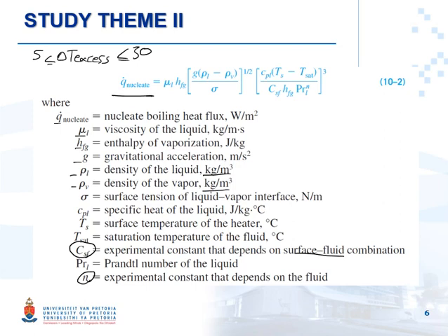I cannot predict how many nucleate sites we can have by knowing the temperature or the surface, or where the first bubble will form, or how the bubbles will behave. That's the reason it's very complicated to understand the nature of nucleate boiling and come up with any kind of mathematical correlation for heat transfer based on pure theory.